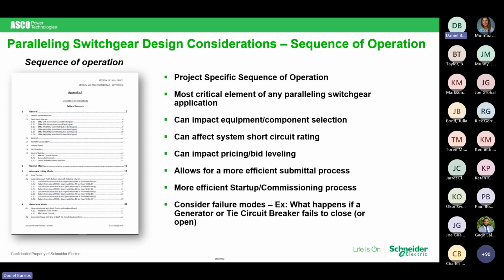One of the items that got added is that I'm going to put a load bank in there. And when I'm in a certain type of scenario, I want to adjust my load bank up or down so that I maintain my 30, 35, 40% on my generator while I'm doing my JCO testing. That may not be in our standard sequence of operation. We're more than willing to work with you on that to put any specifics in there.